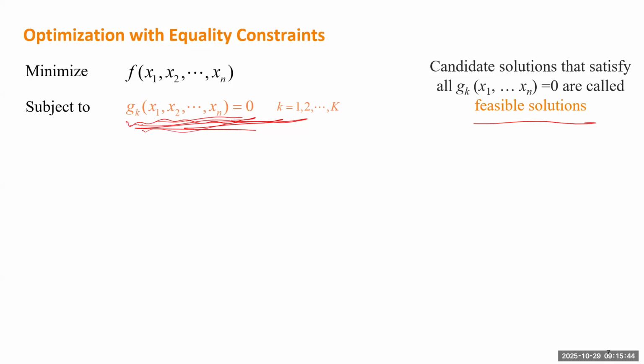If there are multiple normal conditions, then we want to find out how to minimize this cost function. We find the state with the minimal cost among all the feasible solutions. So that's our goal for economic dispatch. The logic is that finding a feasible solution is not too bad. It's okay. That can at least guarantee the reliability of your system. If you have more room to choose between different solutions, we want to find the cheapest one with the minimal cost.